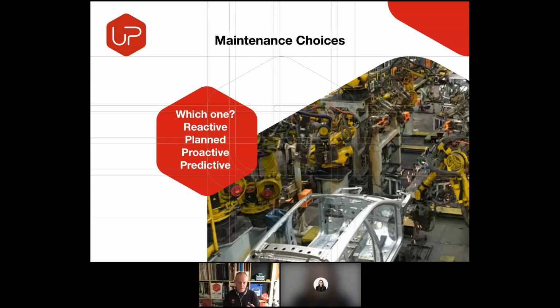So that's the second approach. You can put in lots and lots of time-based planned things and still have the breakdowns that cost you money. And what happens then is it's like a snowball effect. Once something breaks, somebody says, well, can we go and put a PM in for that and do it every week rather than every month? And you end up with a mass of labor hours you can never cover. And if you're on a KPI chart, you'll never be able to tick the box that said you got your 93% compliance or wherever the figure says.